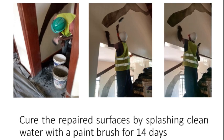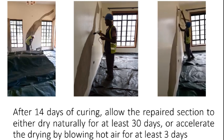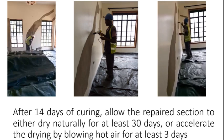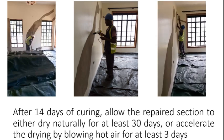You splash carefully, and then of course you allow the repaired section to dry naturally for at least 30 days. You can also accelerate the drying by blowing hot air for at least 3 days. You can blow the hot air depending on the humidity on this area, the humidity within the house. You can blow the area. This is called accelerating drying, or there's no hurry in retrofitting.